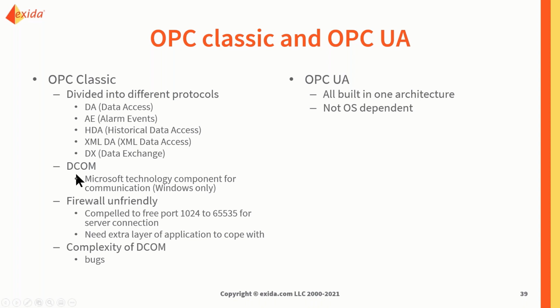The other important thing is that OPC Classic uses DCOM. The problem with DCOM is that it's quite old, and it was developed for Windows only because it's a Microsoft technology component.